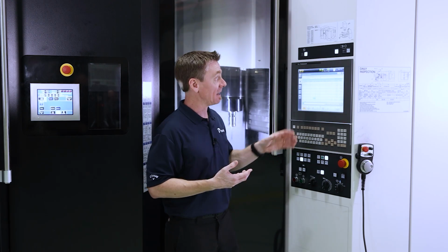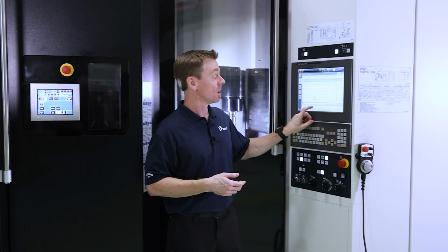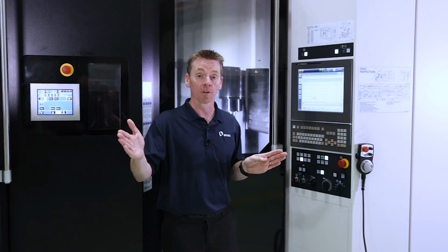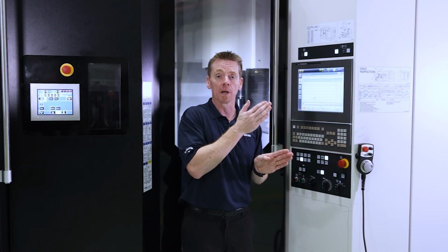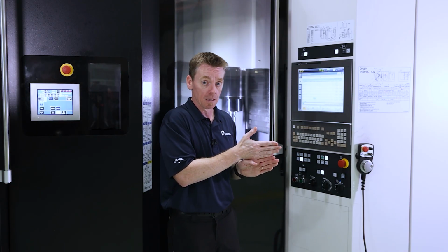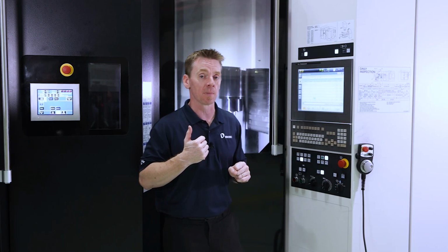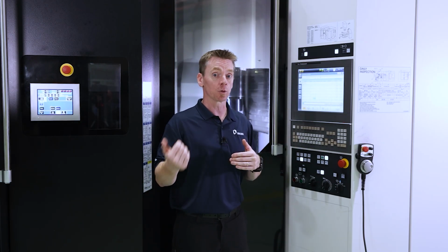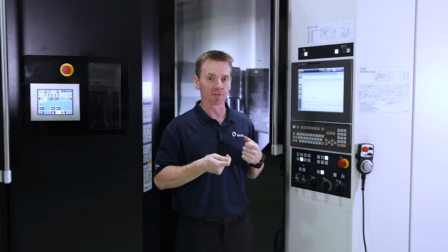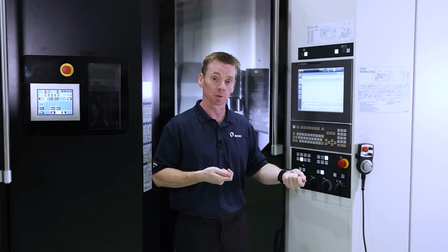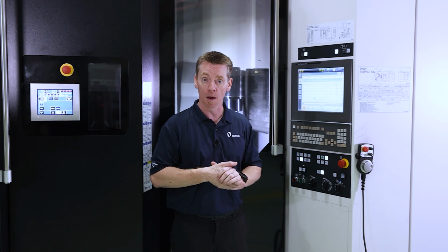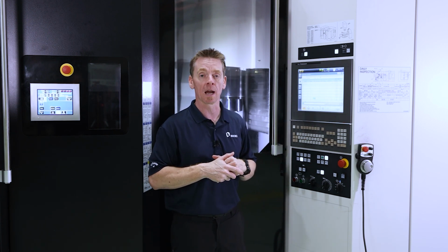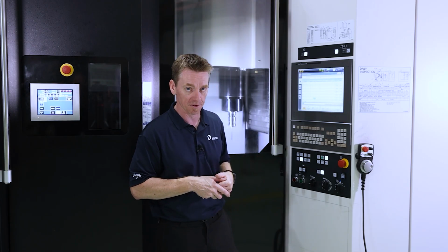The way to get away from that is with the Makino tool data page, where we can start with a 4-digit number. You could start at 1000 and work from there, thus breaking the correlation between a pot number and a tool number. If I have 5 tools to put in the system, I no longer care what pot number they go into because my tool number is completely independent. I just look for empty pots, stick the physical tool in, and then assign the correlating number under the tool data, thus telling the programs in the machine to call those tools by those numbers.